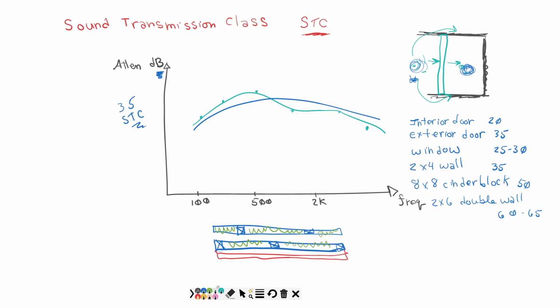And to make it even extra special, in between these, we will put in a viscous damping compound. So this would be something you would apply with like a caulking gun, right? You would put up the first layer of drywall and then you would squirt this viscous stuff all over it.